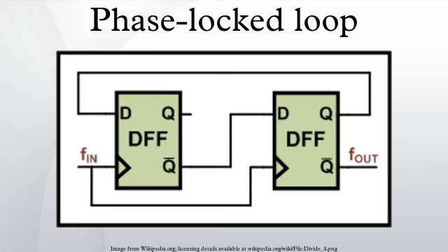Jitter and noise reduction: one desirable property of all PLLs is that the reference and feedback clock edges be brought into very close alignment. The average difference in time between the phases of the two signals when the PLL has achieved lock is called the static phase offset. The variance between these phases is called tracking jitter. Ideally, the static phase offset should be zero, and the tracking jitter should be as low as possible.